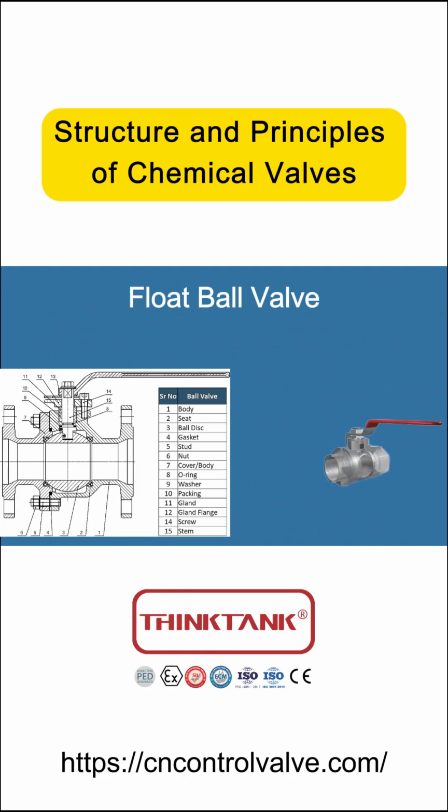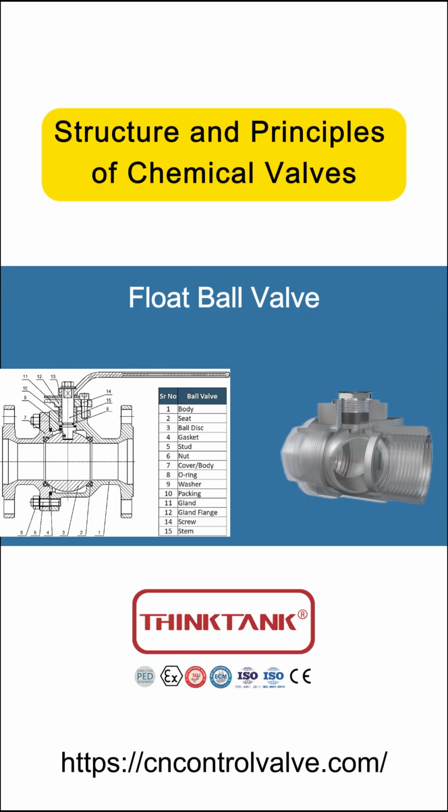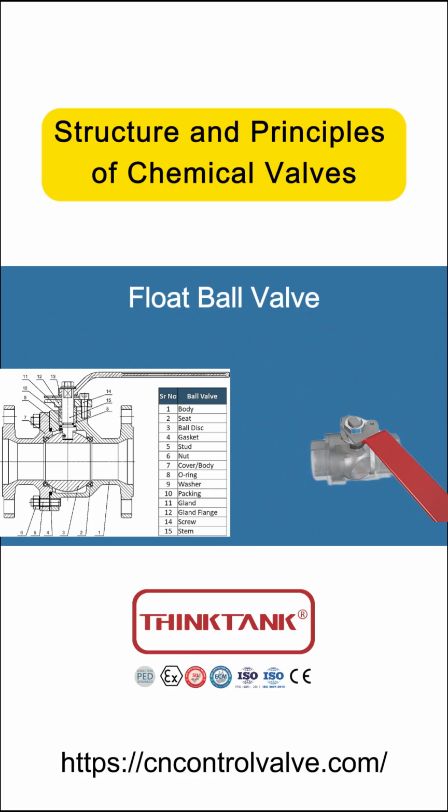A floating ball valve. The ball has no support shaft at the bottom. It is supported by the two valve seats. When operating under pressure, the ball will shift slightly toward the outlet seat. If the pressure is too high, it will accelerate the wear on the sealing surface.